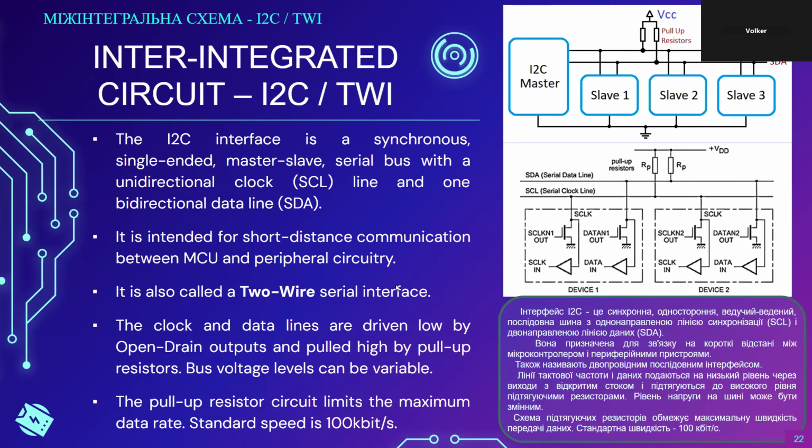You would have to reserve 2 separate I2C buses, one for 5 volt and one for 3.3 volt. But I'm just pointing out that generally, check out the data sheet of the microcontroller that you're intending to use, and more often than not, the pins that are intended for I2C lines are 5 volt tolerant.